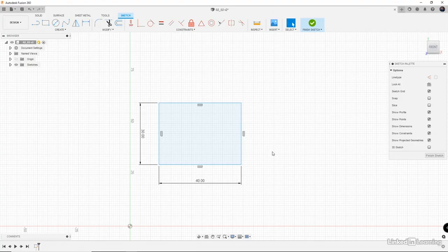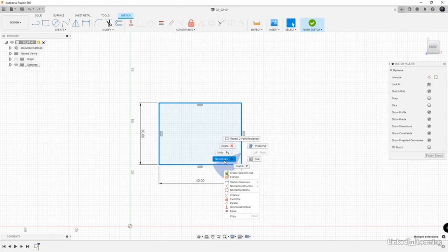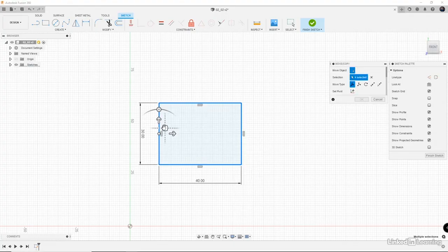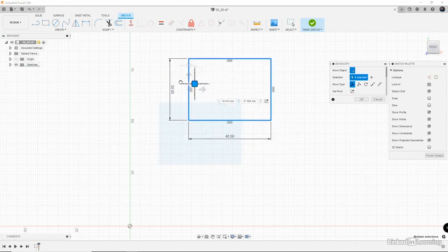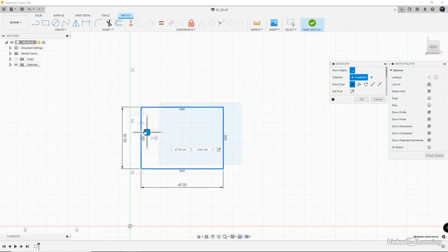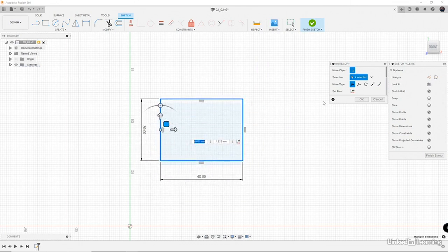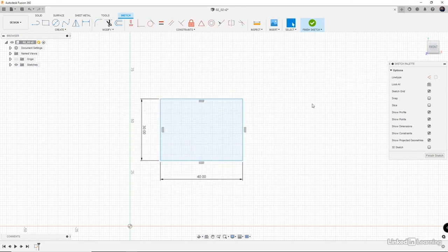This means that this geometry is not fully constrained, because this geometry, if we right click on it and hit move, can be moved anywhere in this plane without breaking any of these rules. So let's just move that there. And now if we hit D and create some simple dimensions real quick, we can do a width here, and let's do 15. And then let's do another dimension.